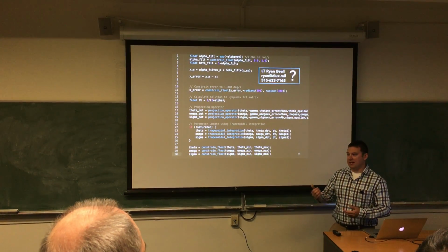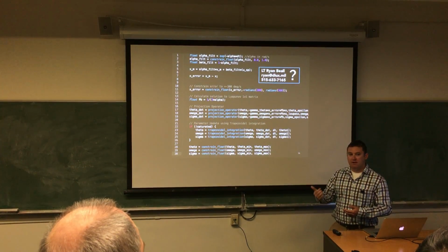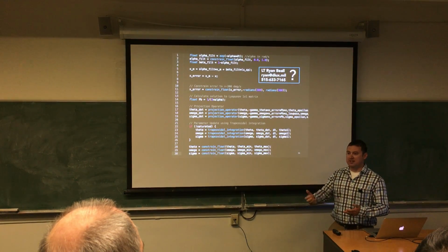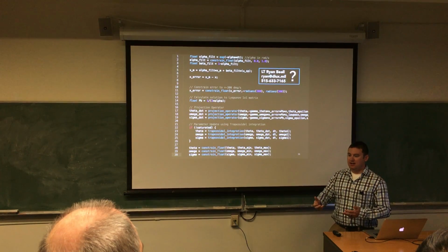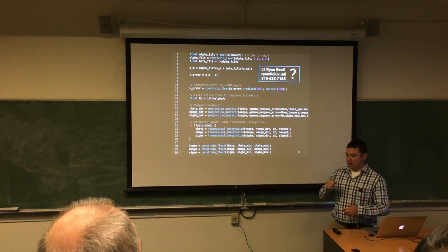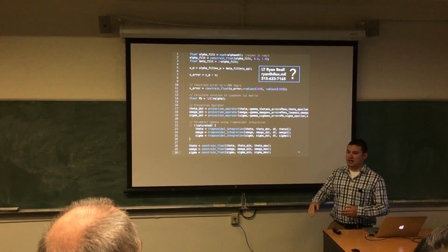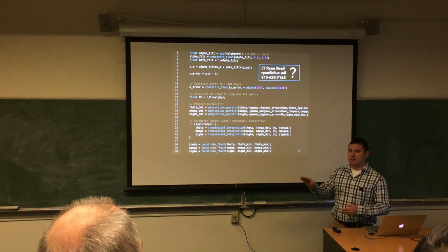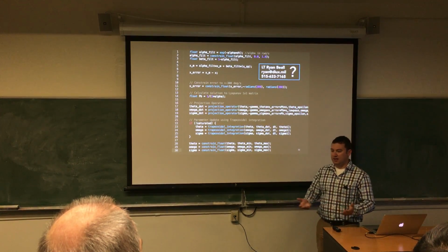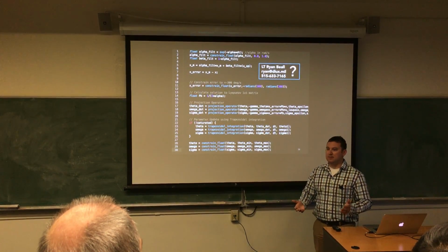Some of the other ones, like the steady state error that I found in pitch, was by accident. I was wanting to just prove the step response of PID versus adaptive control, and I kept noticing every time with the PID, whenever you push the nose down, it would have steady state error on the negative side, but not on the positive side. And then I started doing some research into why that was the case, and found, oh wow, it's not the case in adaptive control.